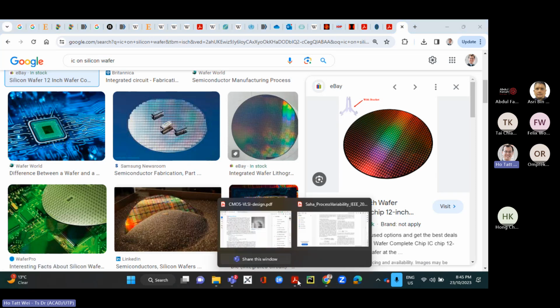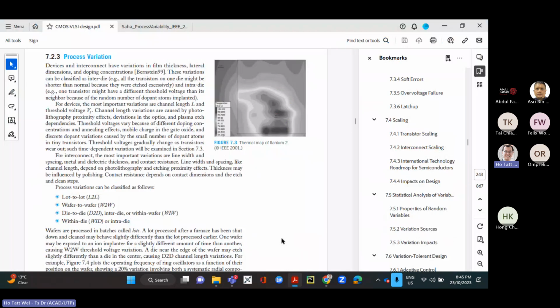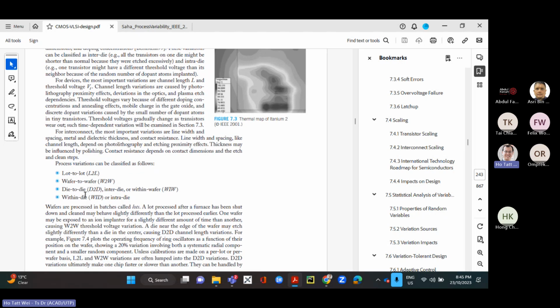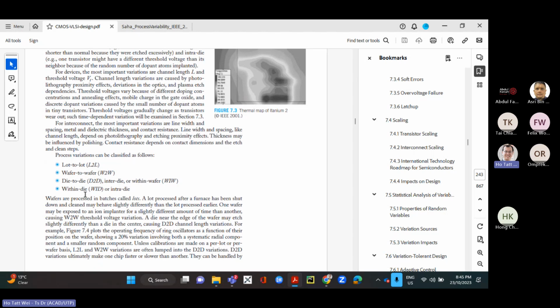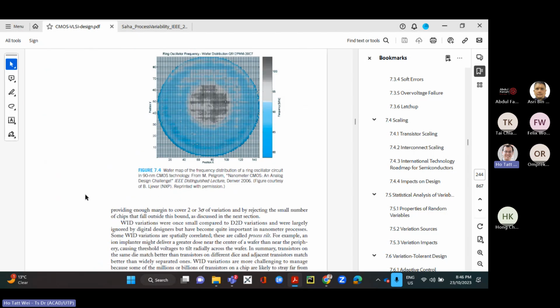And the main message I'm mentioning to you today is that the within-die or intra-die variability is quite significant nowadays. If the intra-die is already significant, no need to talk about die to die, within wafer, wafer to wafer, lot to lot, which are also very significant. Even on one chip itself the variation is so significant because we are already in the domain where things are so fast that from one end of the chip to the other end, the transistor can look quite different. And not just that, the delay for you to send the signals will be quite different. So there are various kinds of variation.